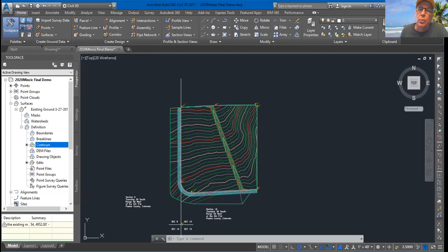The first thing I would normally have done at this stage would be to run an area around the particular area in which I'm going to subdivide. That would be this area that is north of this road, east of this road, and south of this line, and west of this line. That's the area in which we're going to do our subdivision. So I would have run an actual land survey all the way around the corners of that, and actually define that parcel right there and find my overall acreage.